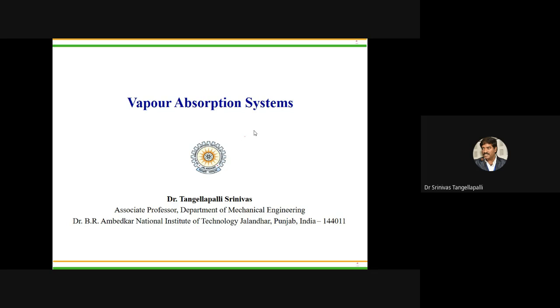That's why the Rankine cycle is termed a modified Rankine cycle, and the reverse Rankine cycle is called a modified reverse Rankine cycle. The very specific name of this modified Rankine cycle is the Kalina cycle, as per the inventor, for power generation. For vapor absorption refrigeration, there is no specific scientist name, so we still call it VR only, the vapor absorption refrigeration system.